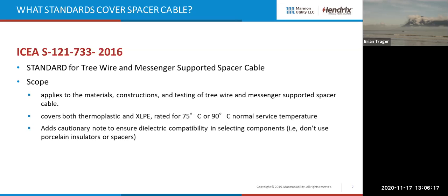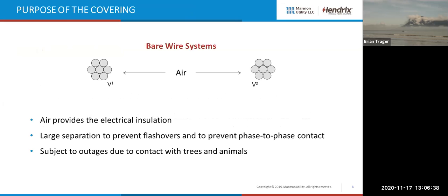And this ICEA, even though it is for a component and not a system, they were prescient enough to add a cautionary note to ensure dielectric compatibility in selecting components, which means don't use porcelain insulators, don't use porcelain spacers, because you're going to ruin your cable. So that was quite nicely done on the part of ICEA.